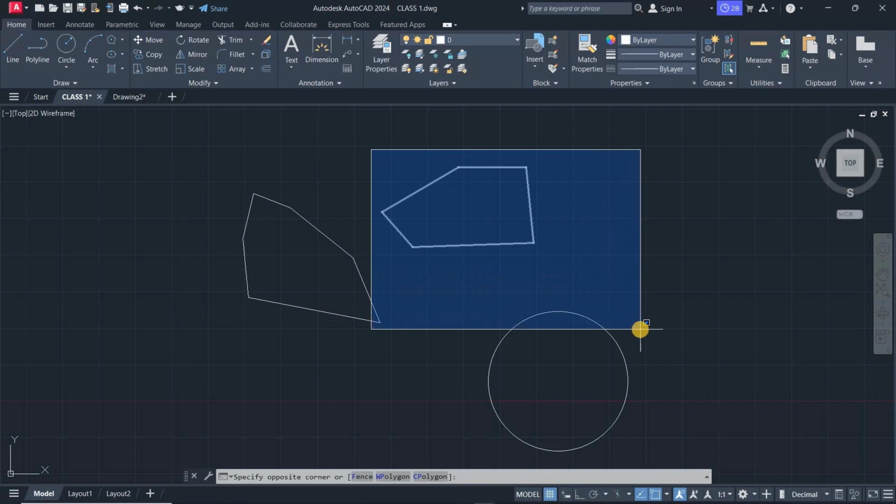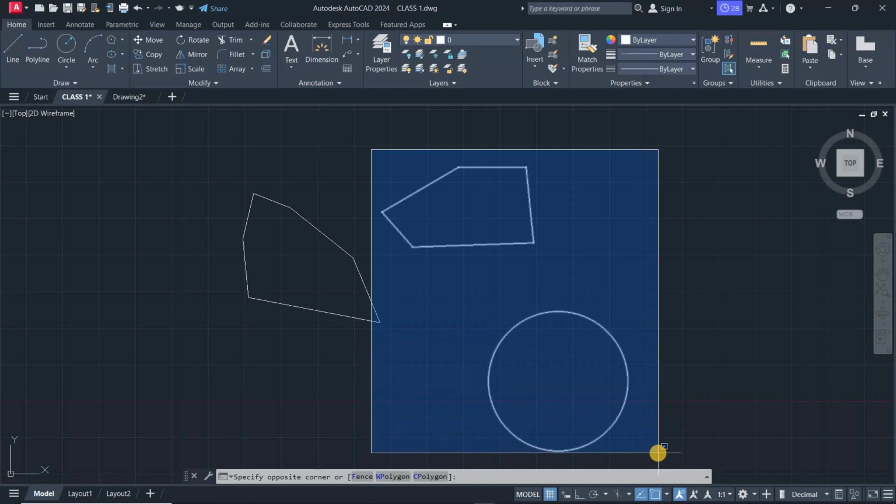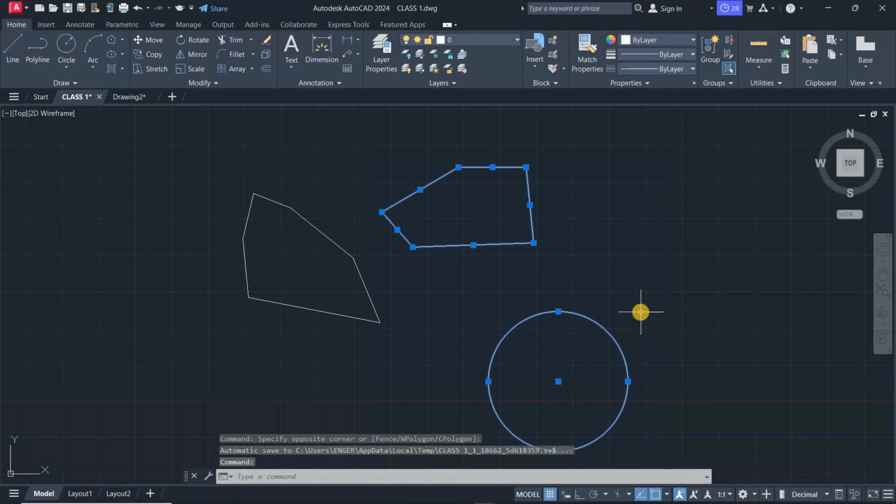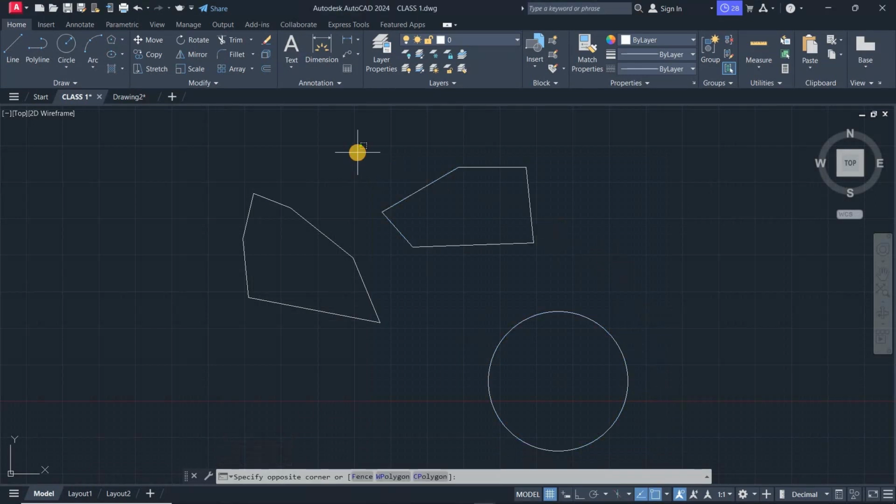That's what is called the solid window selection. In other words, objects that are completely covered by that blue transparent highlighter, when I left click the mouse again, those objects will be selected. Now, if I click my mouse here again, and this time not to the right, but I move to my left, you notice a green transparent highlighter.